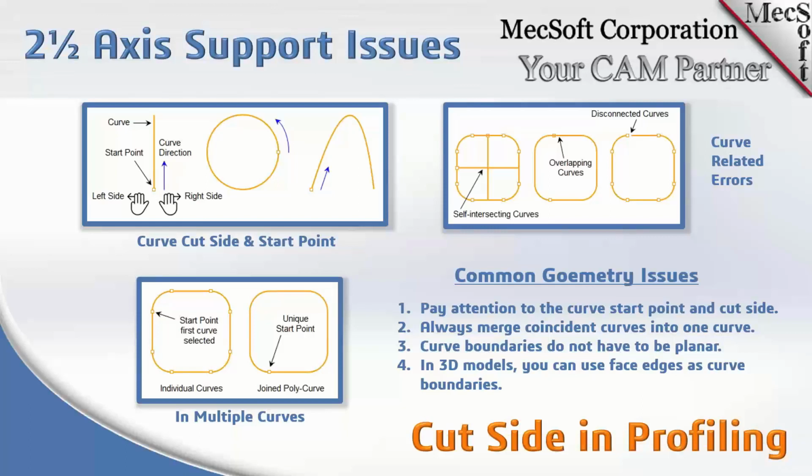For profiling, many times you will not profile a closed circle or a closed square. You may just have a line, okay? So you need to understand where the cut is going to start, and which side of the line the cut is going to be on. If you look at this top left dialog picture, there is a little square box that shows you in the program where the start point of that geometry is.